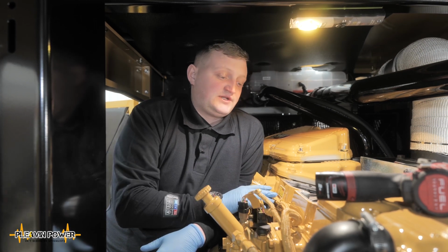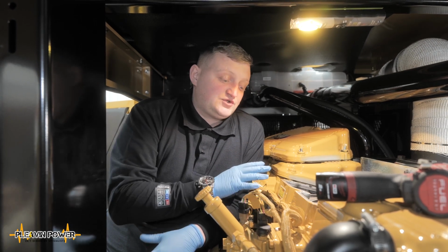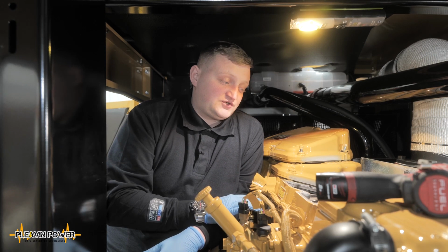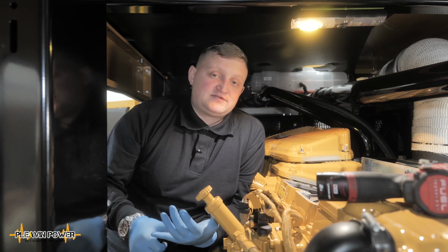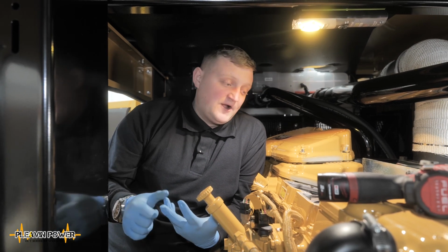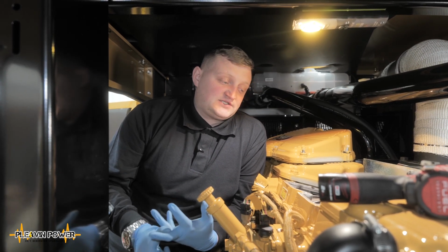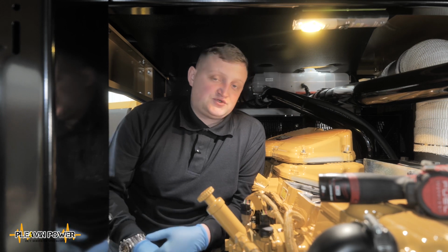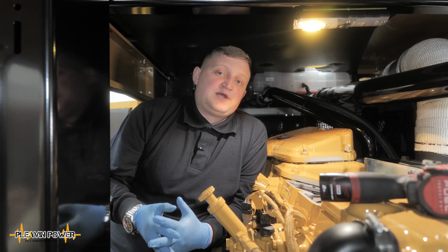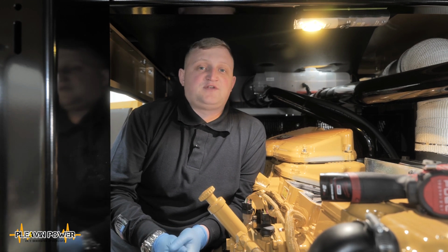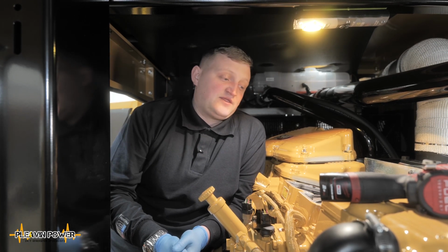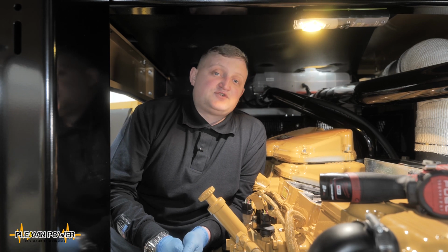Failure to adjust these can lead to failures, and unfortunately, due to the recommended service levels by the manufacturers, they often get ignored. Some of the defects it can cause are dropped valves, intensive wear of the valve seat itself, and also excessive fuel consumption if the injectors fail to be adjusted accordingly. Manufacturer and OEM specifications specify that these valves should be adjusted initially at 250 hours of engine running, and then after every 500 hours.